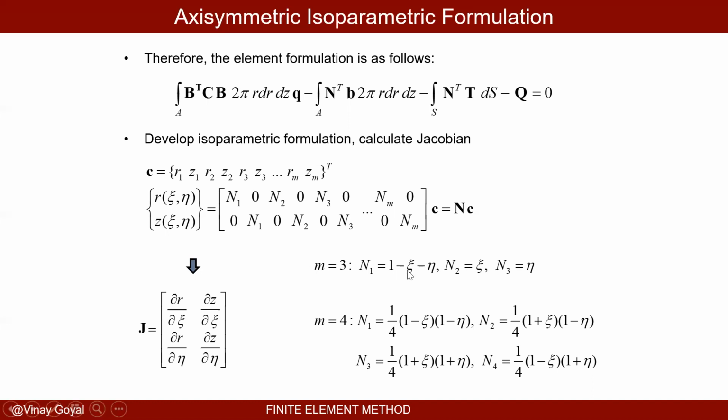So we know that one of the nodes in the standard element is psi and eta equal to 0. So if I put 0 here and 0 here, that's 0, that's 0, I get N1 equals 1. So I put 1 here, 0 here, 0 here, and so forth. What you'll find is that this row vector times C bold will give me that first node. And that is a point. For a triangular element, that's all you have. So it ends up to here for a triangular element. For a quadrilateral element, which is 4 nodes, I will have a block of 2 more, N4, 0, 0, and N4. That's what I get.